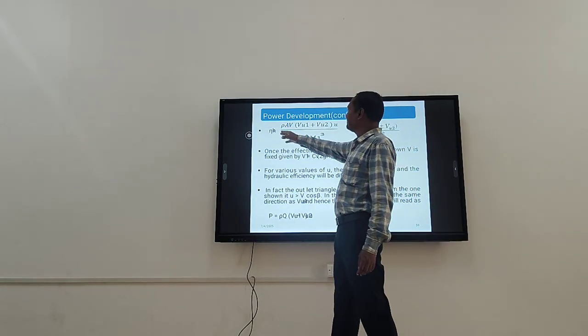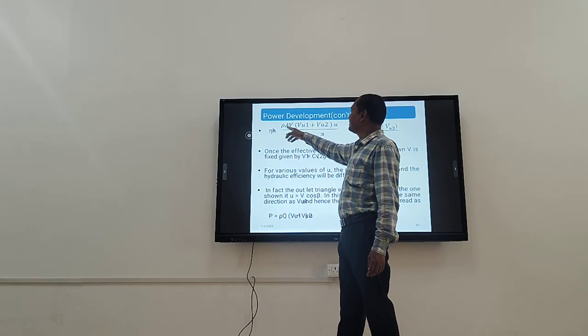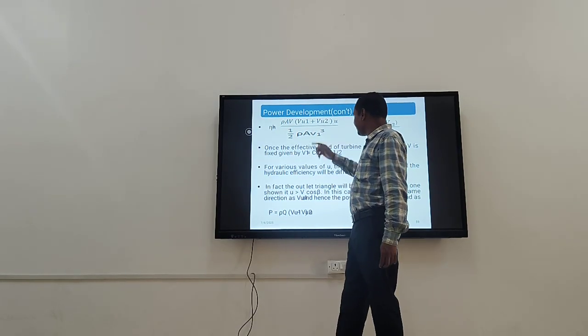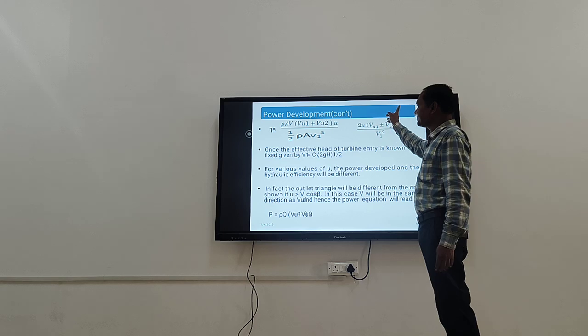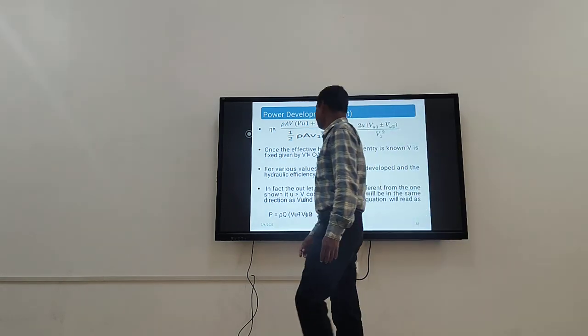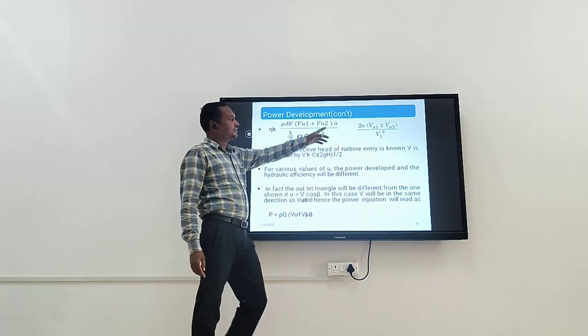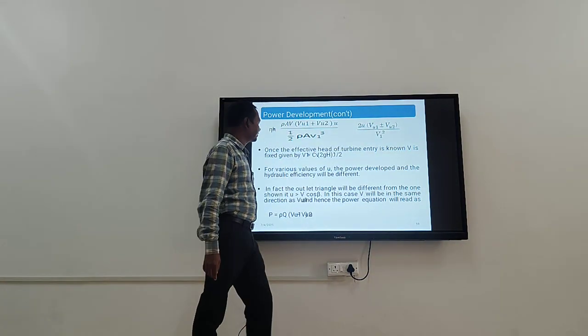So your hydraulic efficiency is given as the work done divided by the input jet energy. Finally you get this one, that is 2U multiplied by (VU1 plus or minus VU2) divided by V1 square.